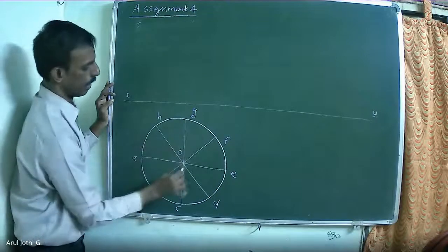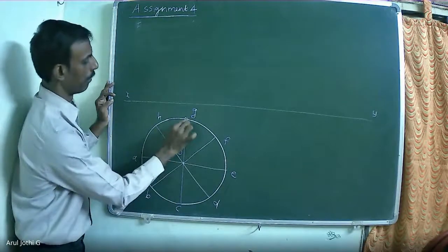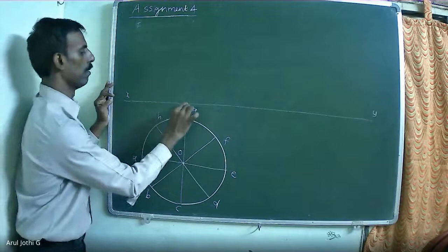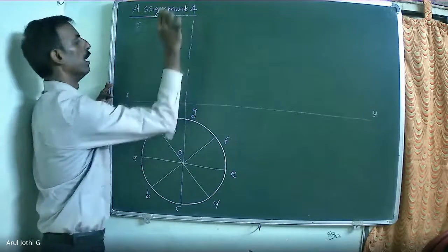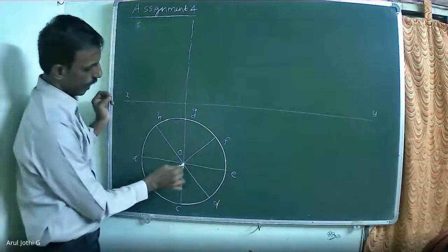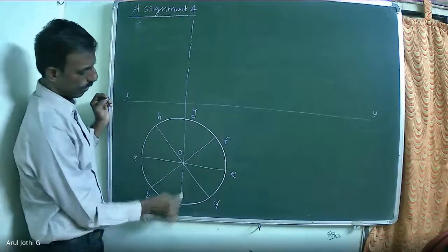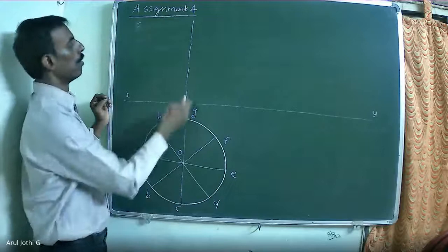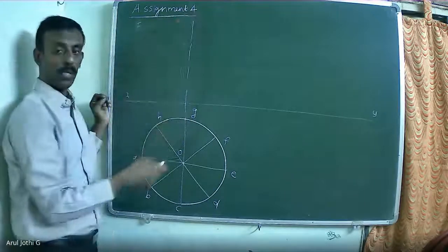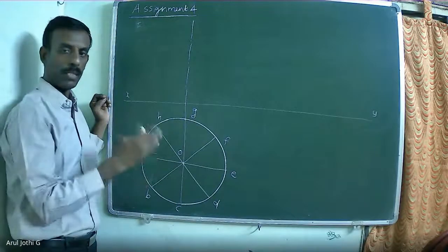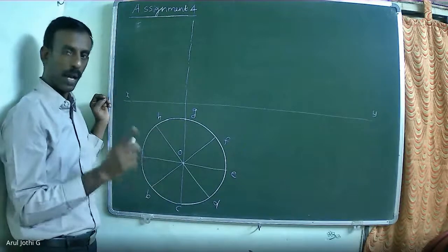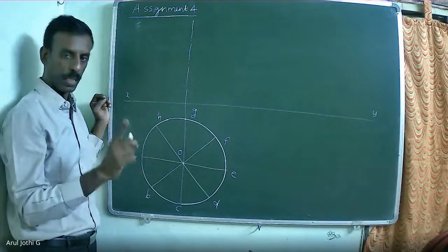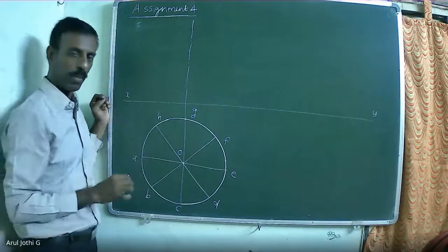Now extend the axis line to the front view and draw the axis line. For the cone and cylinder, this axis line is coinciding with the generator OC, so you have to give priority to the axis line only. When the axis and the generators are coinciding, you construct the axis line alone, not the generator, but you give the notation for the generators.